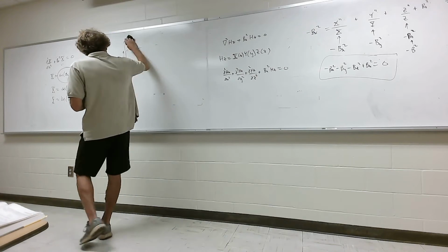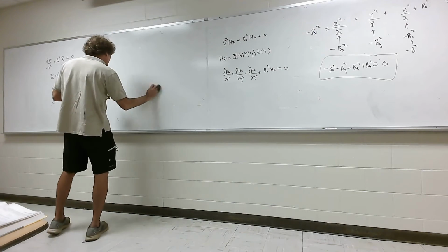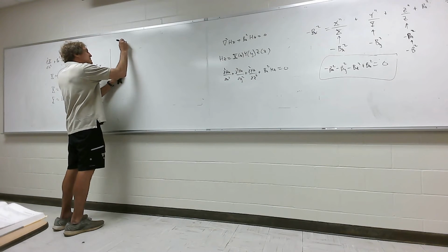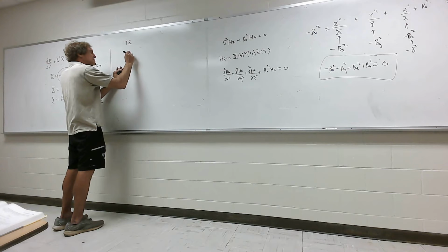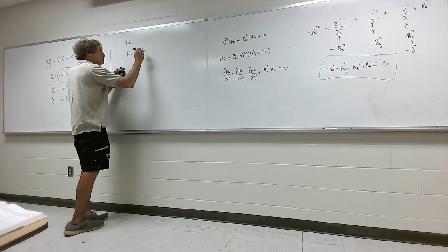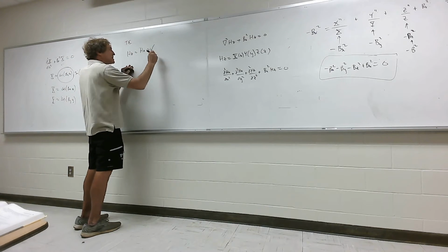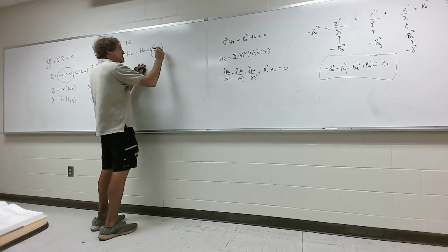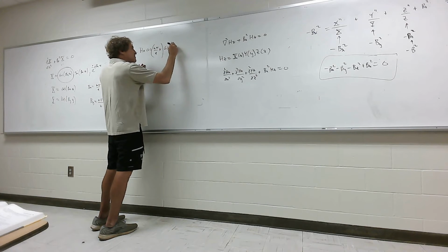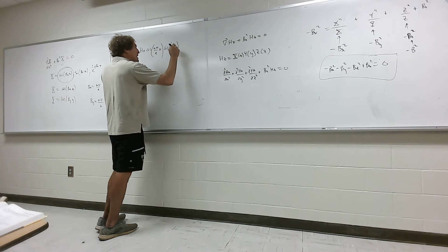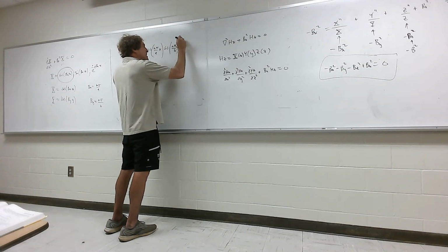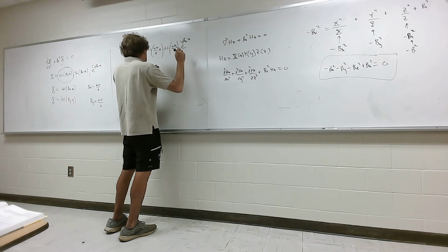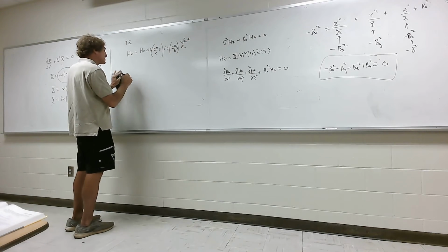And this is important. When we go through this whole thing, we find out that now our HZ, for the TE mode, HZ has the form of some H naught, just a constant, times cosine of m pi over a times x, then cosine of n pi over b times y, and then e to the minus j beta, I like to put beta z, times z. And this would be HZ.